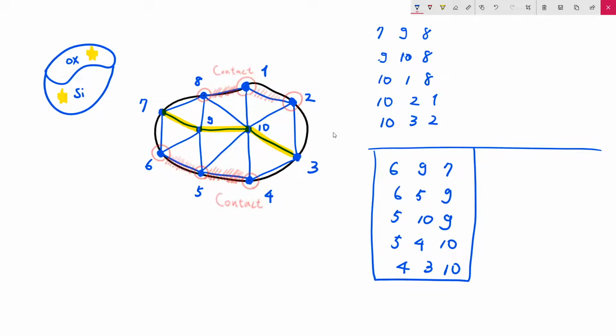One specifies the lower region, which has silicon permittivity, and the other specifies the upper region, which has the oxide permittivity. Of course, you have to introduce two separate descriptions for them and read them sequentially to construct the whole system.